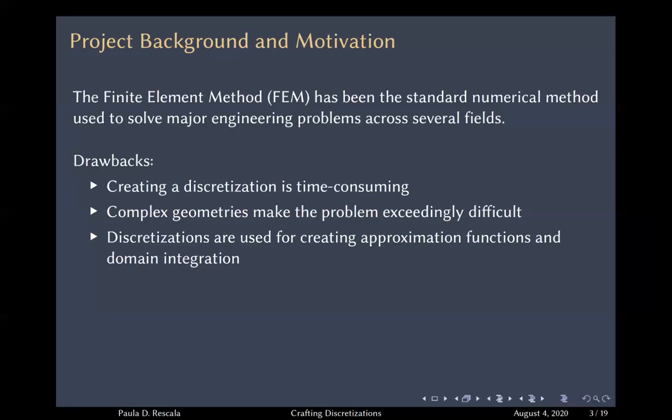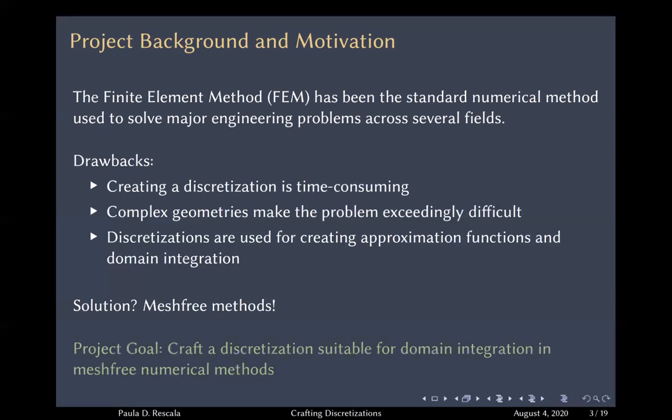So the solution to all this that has been developed is the implementation and creation of mesh-free numerical methods. For example, the conforming reproducing kernel method is a mesh-free method because it does not need this discretization for creating the approximation functions. Rather, it is used solely for domain integration. The approximation functions are created on a point cloud, and so the quality of the mesh is not as tied to the quality of the solution as in FEM. So my project is actually to refine the meshing process and make it more effective with the goal that it will be suitable for these mesh-free methods.